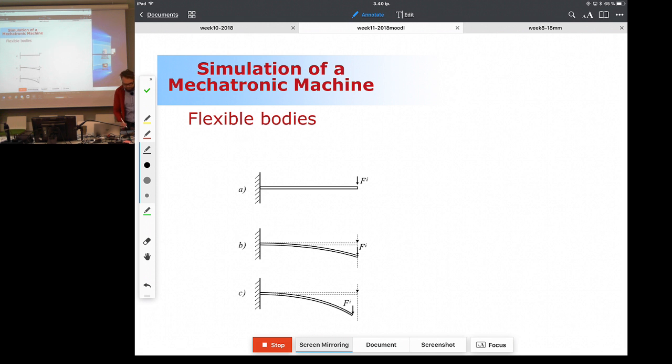You know from finite elements that if you have a displacement of one point here, using the displacement you can compute the strain in any location of the structure. The nonlinearity is related to the relation between the displacement and the strain. If you deal with small deformation, the deformation that is not so significant, this relation can be assumed to be linear.